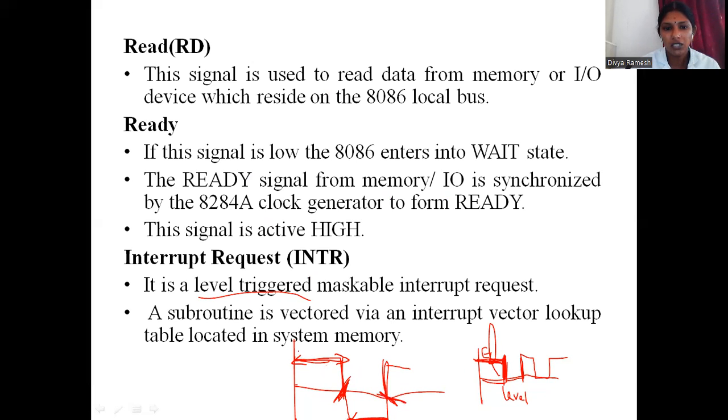Coming to this one, it is edge triggering. The waveform has a positive edge and a negative edge. That is the edge triggering. Level triggering, in a sense, once the positive cycle has ended it will meet the zero point, and it will take it into consideration as a positive level trigger. So this interrupt request is operated depending upon the level triggered input. Whenever a positive level is reached, it starts to trigger and accept the data.